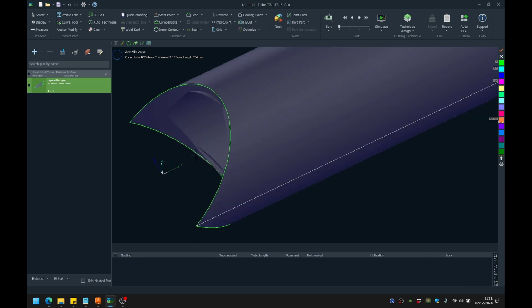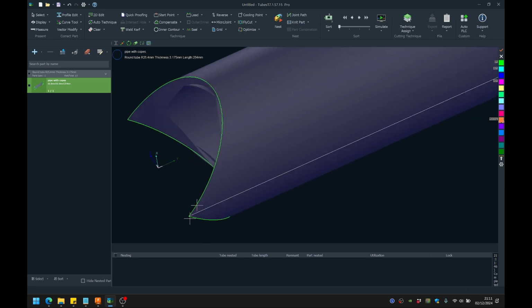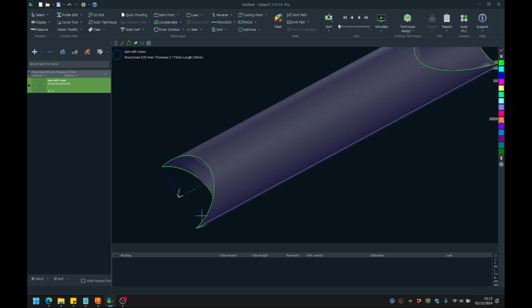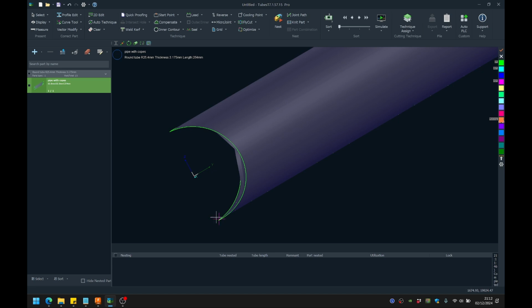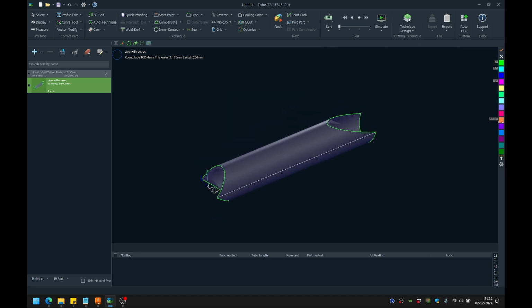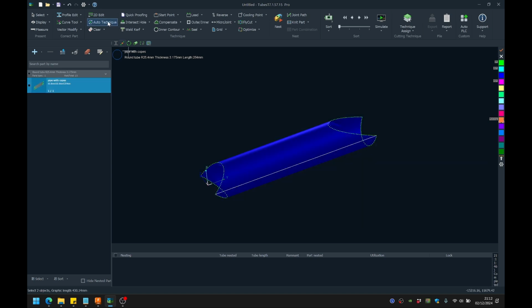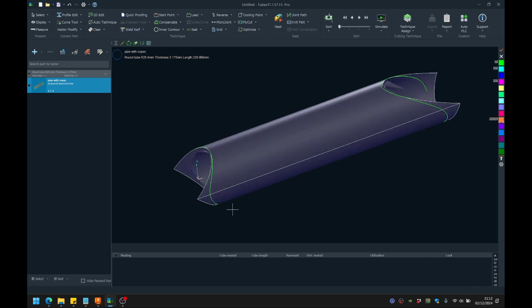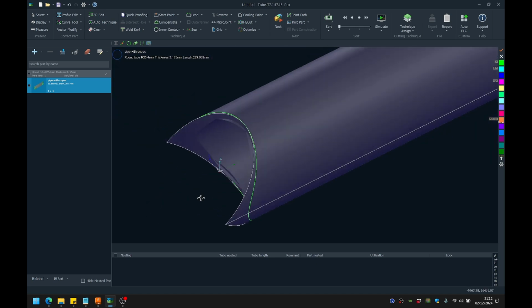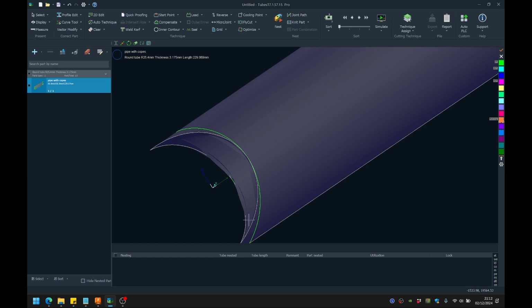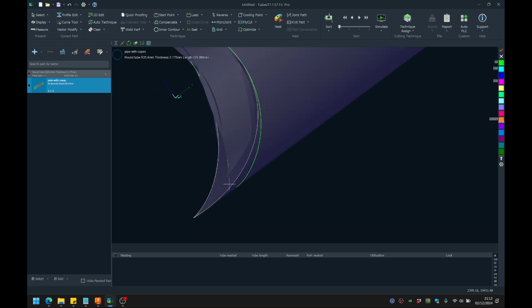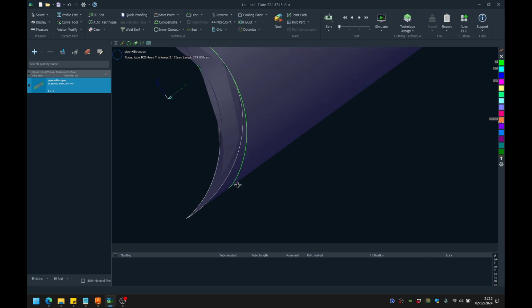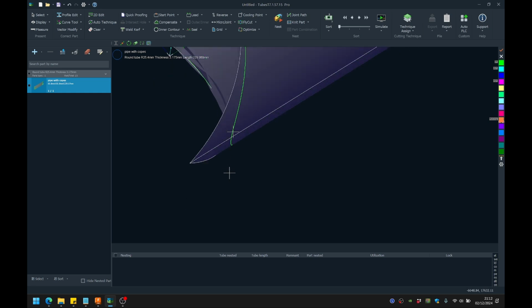Now this won't work very well because the copes are sharp, and if your head is straight, you know that you'll have extra material on this side. So TubesT has an option to fix that, so just select the whole pipe and click on weld curve. Weld curve will compensate this material excess and move the path into the inner surface of the material. So here is where the wall thickness matters. So that's how it knows how much to move it in.